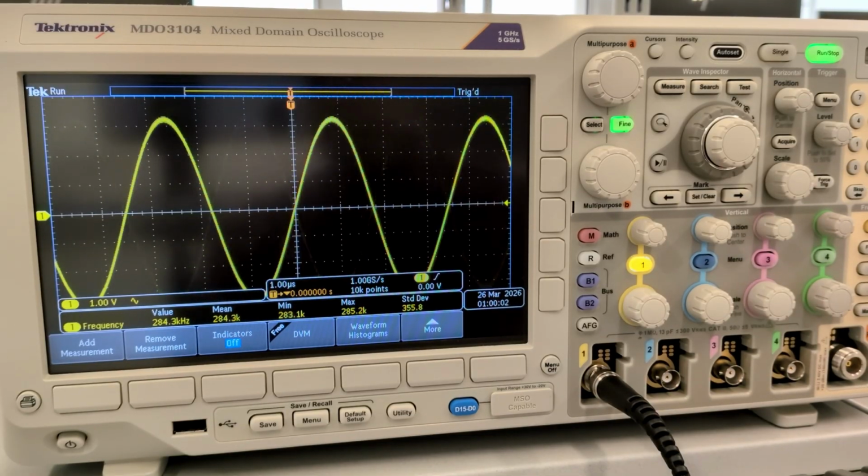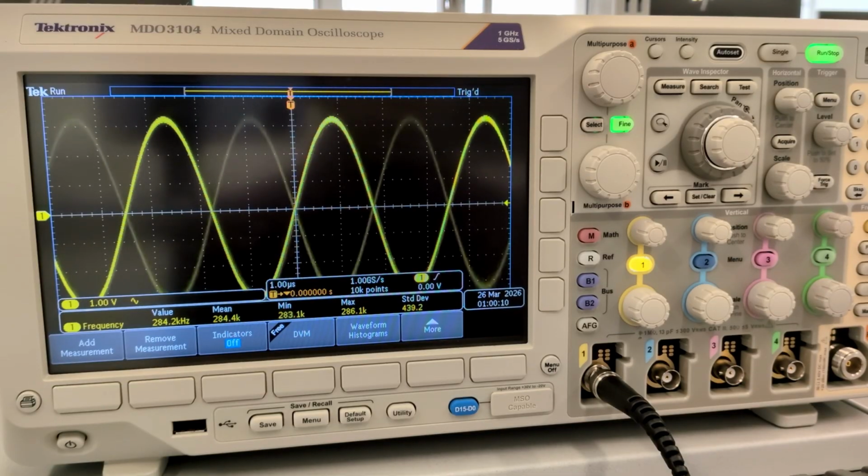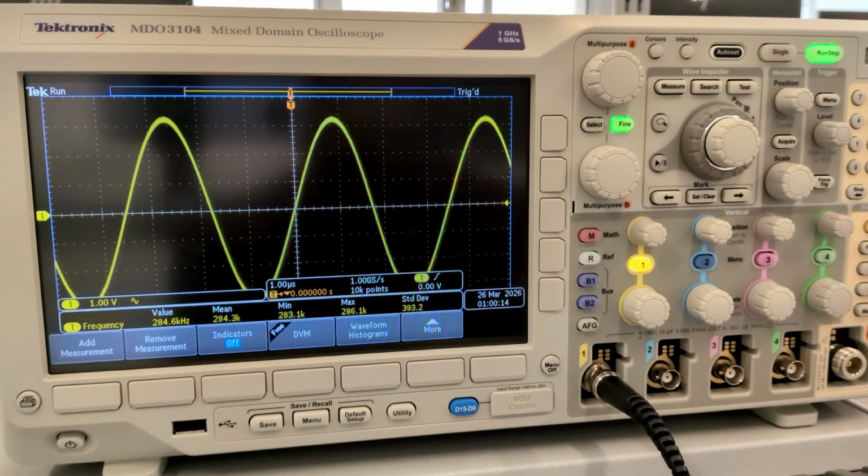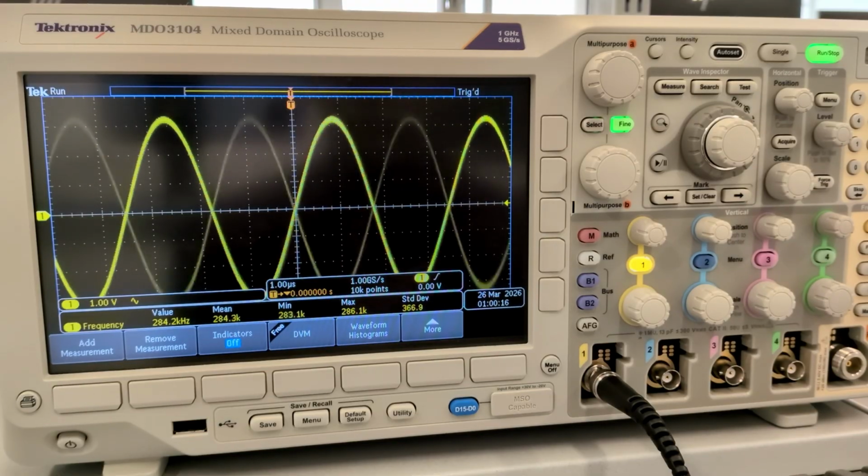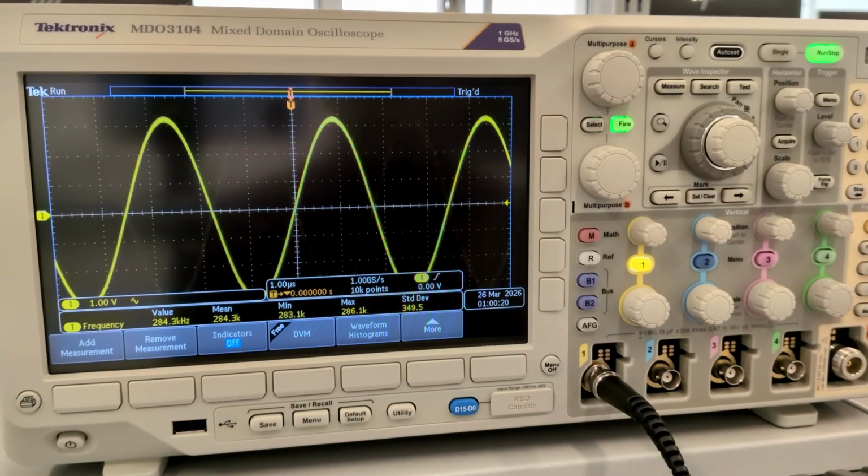Meanwhile, our function generator, I'll go ahead and give this away, also has a little termination resistance on the bottom near the outputs, and it says 50 ohms. That mismatch can sometimes cause your amplitude measurements to be completely out of whack. We'll play around with a few settings where I can show you how we can fix that.